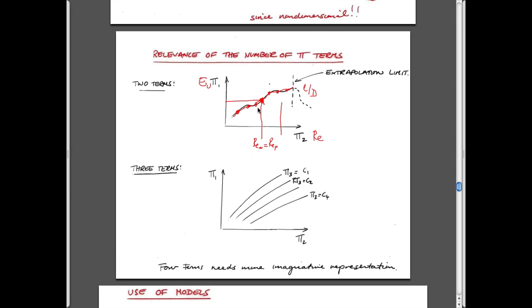But dimensional analysis is really just that. The three tenets: the model has to be a model, same geometry. The model has to be run at the same Reynolds number. And so in other words, you can run a model at a whole bunch of Reynolds numbers and get this curve, so that when you look at your prototype, you always have the right Reynolds number to get the Euler number. If you have the Euler number, you have the pressures on the structures: lift, drag, pushing the antenna over, etc. And so that's basically the idea.